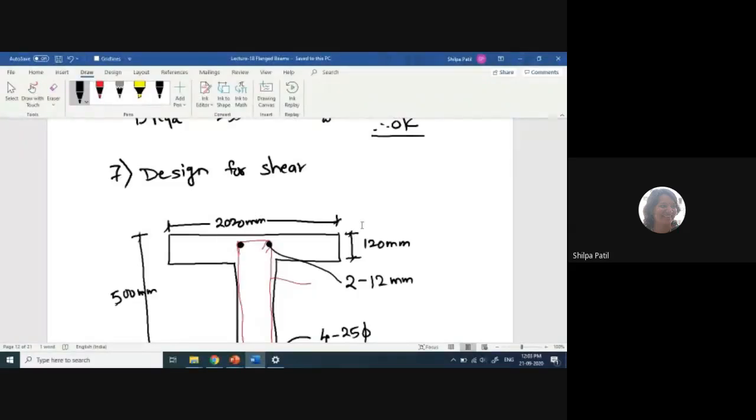If you are using mild steel, then Fy will be 250. If you are using Tor steel, take Fy equal to 415. So you have to specify both in the design. Okay? Yes, ma'am. And is there any criteria to select which one we have to use? No criteria. And we don't have to do the curtailment in this question, no? For design of beam, no need.